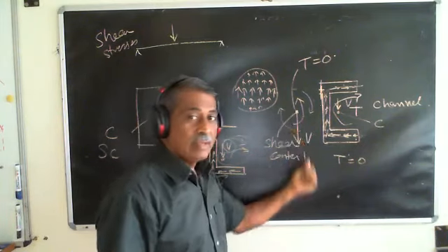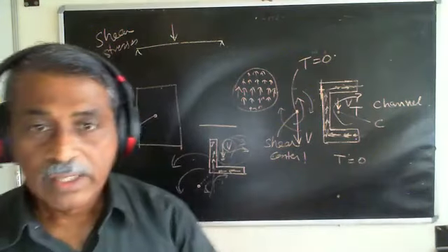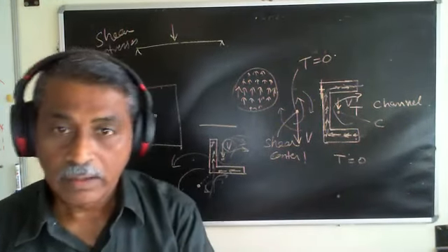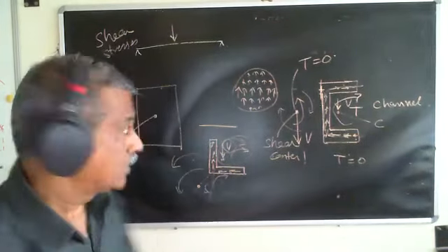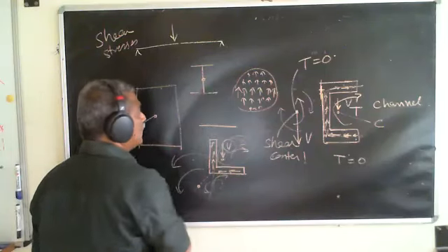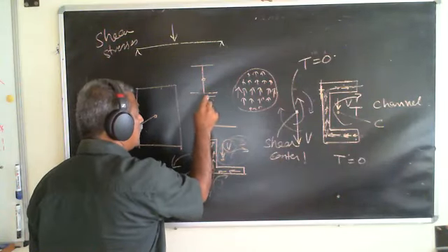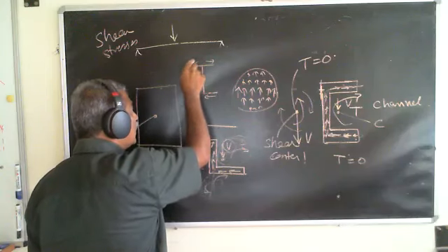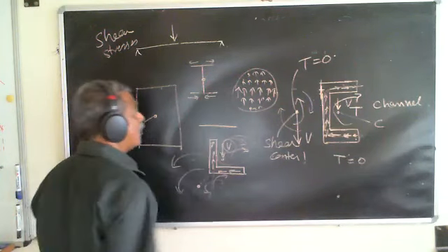Where do we apply the transverse load? Okay, is a very important question when it comes to beams, right? Beams of what? Beams of unsymmetric cross section, because we found that if it is an I section, the centroid and the shear center will be the same, right? Because I have one like this, I have one like this, but I have one like this and one like this, which cancel each other. And the center one, I don't have to bother, right?